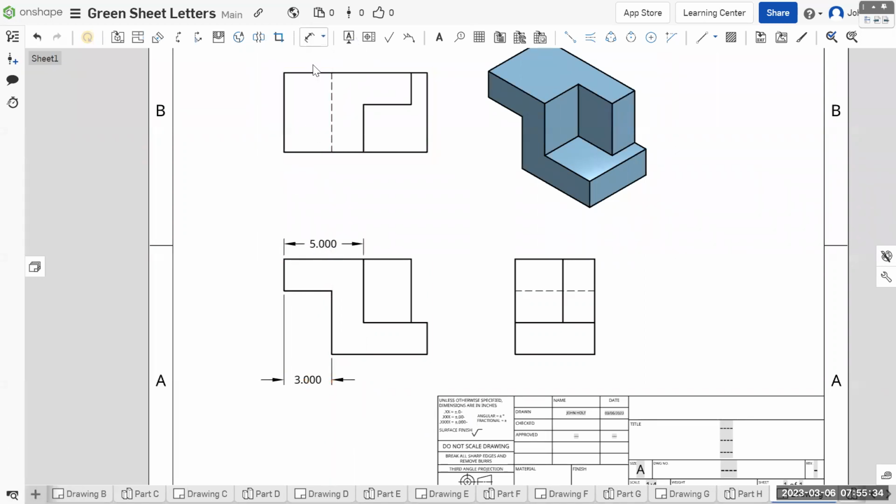And going back to the left, the next thing that happens is where this happens, which is as good as it gets. It's to a contour. It's to the silhouette of the shape. Doesn't cross over between adjacent views. Excellent. And the last thing that happens is the total width, which this is fine. It's between adjacent views, goes to a contour, which total width always goes to a contour.